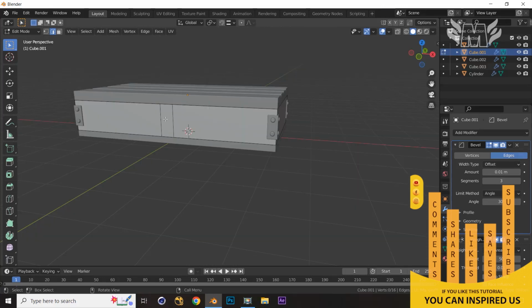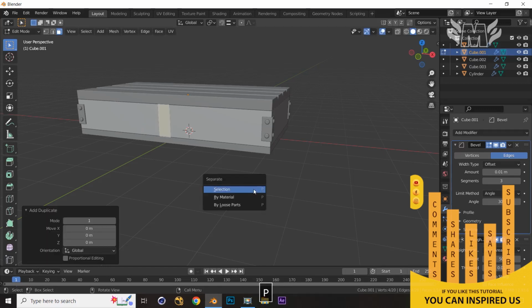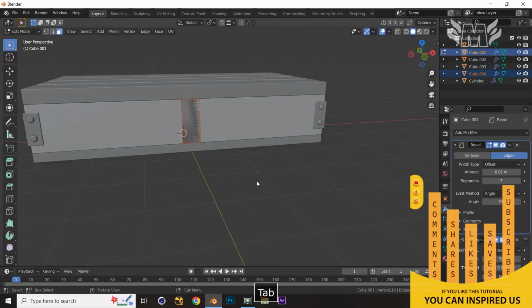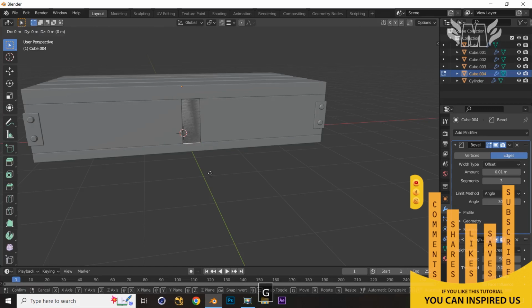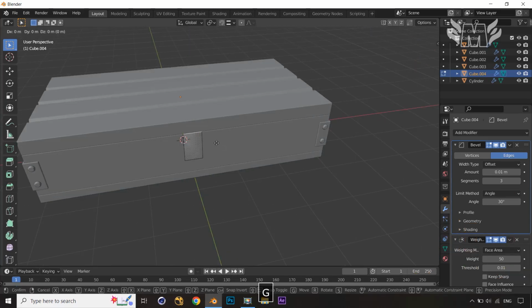Okay, it's going good. Again select the face, and now press Shift and D. Now make it P and selection, so it's different now. Come out over here, select this, jump into that, and now let's make a selection over here. Press 2, select the bottom loop, G and Z, take a little bit up, something like over here. Okay, it's good enough. Now let's select this loop over here and press G and Z, and our snapping is on, so it's properly getting over here.